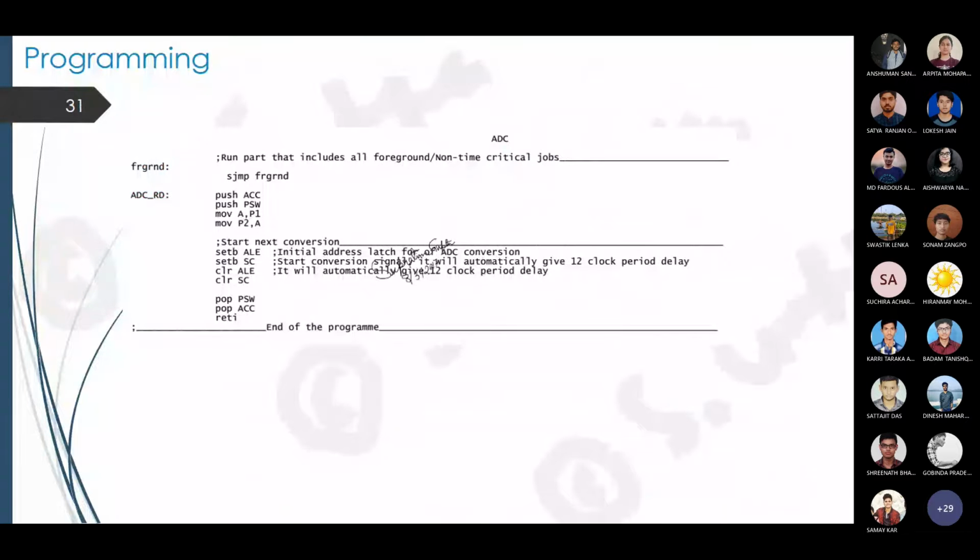So we are not doing anything in the polling mode. And what we have to do here is push and pop. This is just to ensure that if anything is inserted here, that particular operation is using the accumulator, so it will not hamper that process. Very often, because of these, our functions get stuck or malfunction, and then we are unable to do some debugging operations.